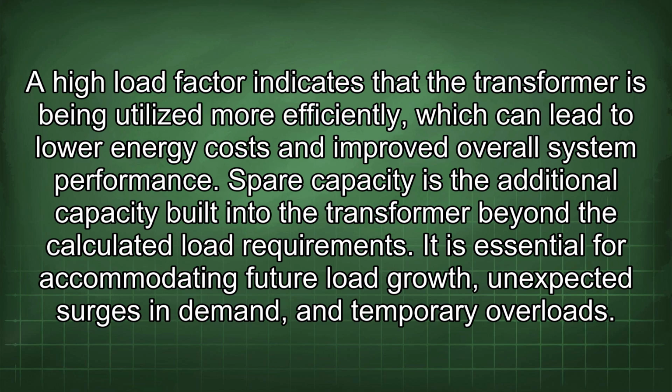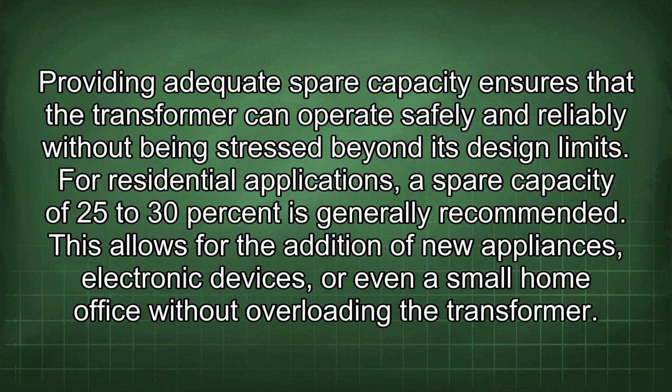Spare capacity is the additional capacity built into the transformer beyond the calculated load requirements. It is essential for accommodating future load growth, unexpected surges in demand, and temporary overloads. Providing adequate spare capacity ensures that the transformer can operate safely and reliably without being stressed beyond its design limits.